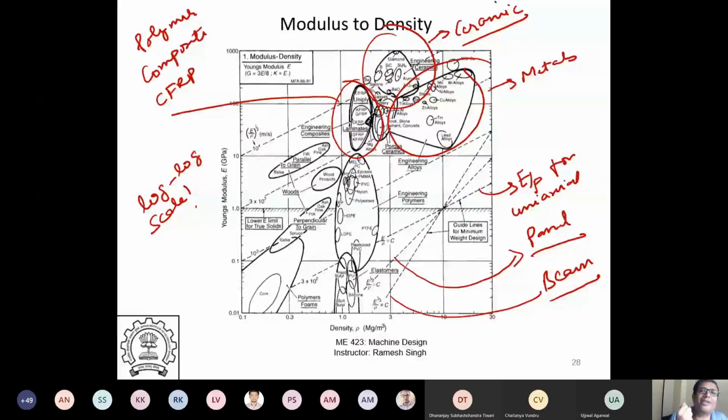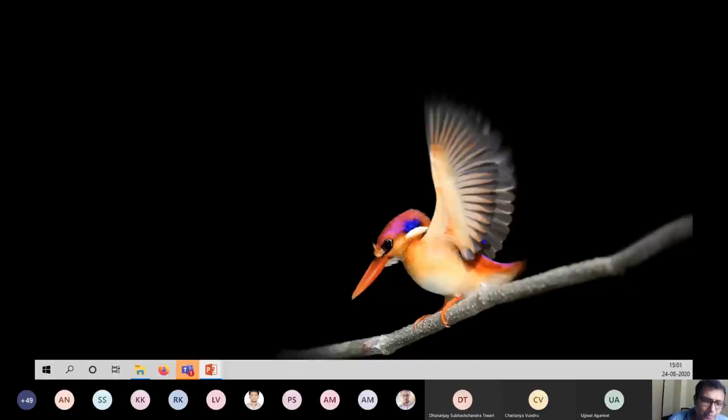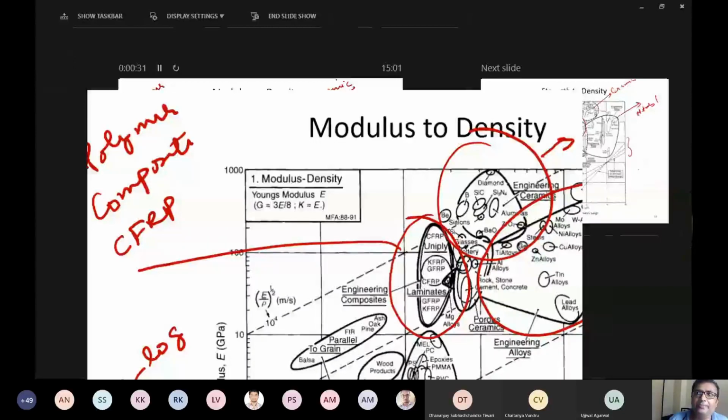It gives some degree of ductility. Or more than ductility, it gives us some impact strength. So it can be deformed. So that's what happens with this thing. And this pre-preg, you can lay out. So either you can do a hand layup with the mold, or you can do something called tape laying, which you saw. So the modern day thing is people do tape laying. Tape laying is the new thing which people do every time.